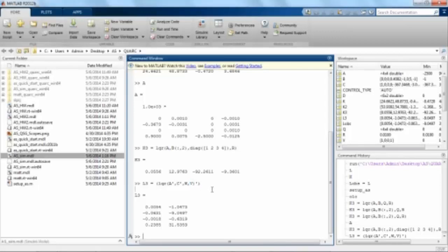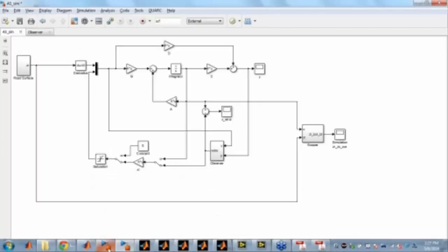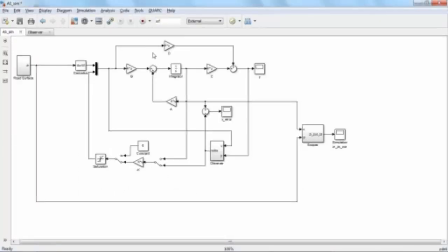These are estimated covariance matrices of our noise values. So to go in a bit more detail, our W basically captures what we expect our system noise to be, and our V matrix captures what we expect our measurement noise to be in the system. So this is something that if you want to simulate it quite nicely, you can, for example, just add some Gaussian noise here for our system noise and some Gaussian noise here at this node for our measurement noise, and you can kind of capture it and see if it all works.